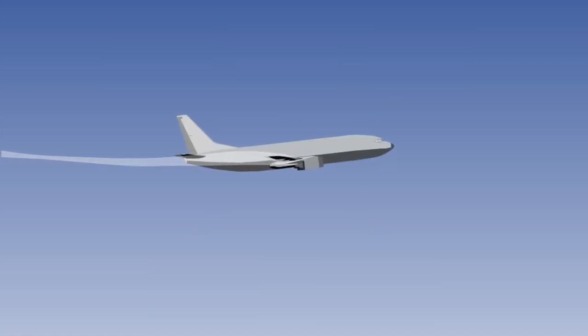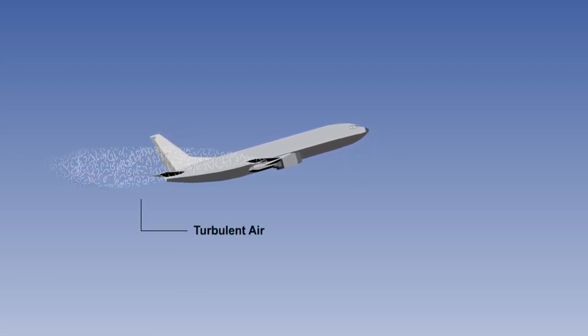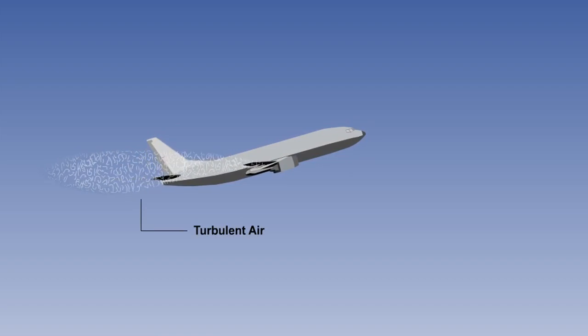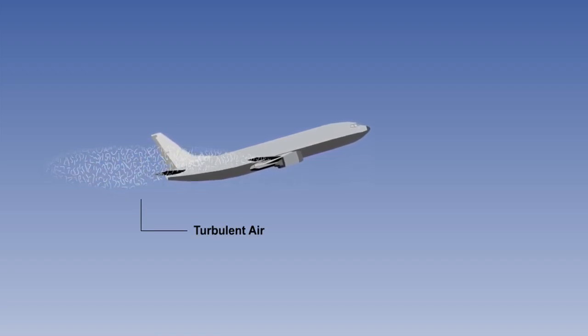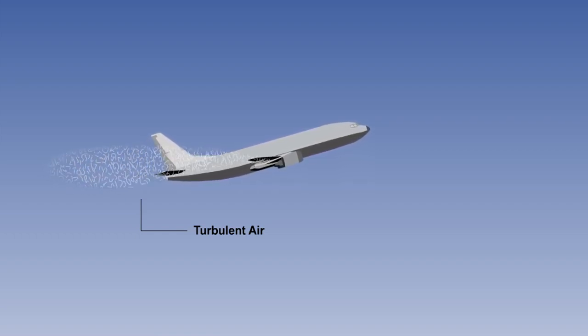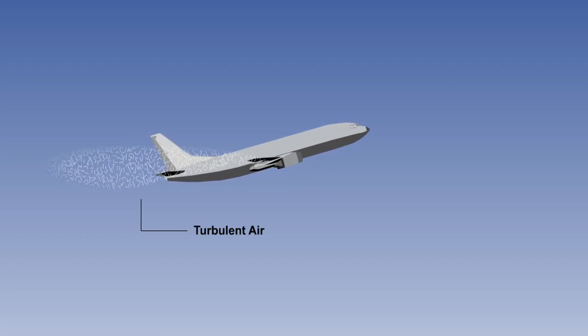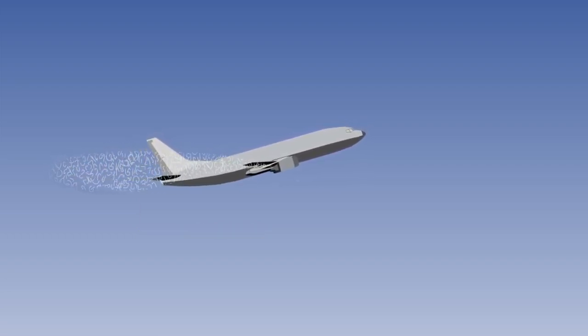There are certain circumstances when a high angle of attack is desirable, like ground proximity or wind shear, to name two. In conventional aeroplanes, under these circumstances, pilots are advised to pull the nose up until they reach stick shake and maintain this attitude. For a pilot to maintain the ideal flight path is not easy. Pull back too much and the aeroplane enters a stall. Not pulling back far enough would not achieve the best climb angle. Either situation would lead to an accident.